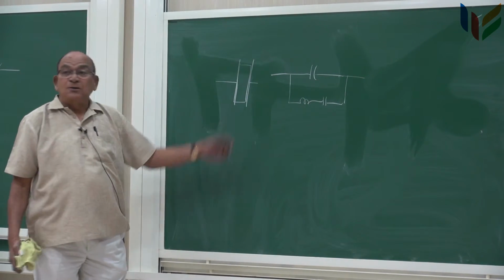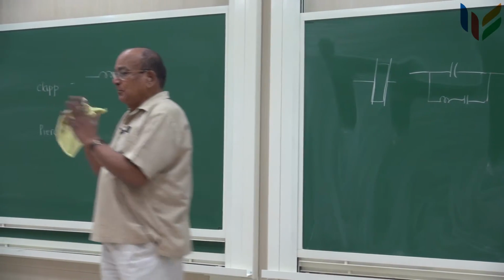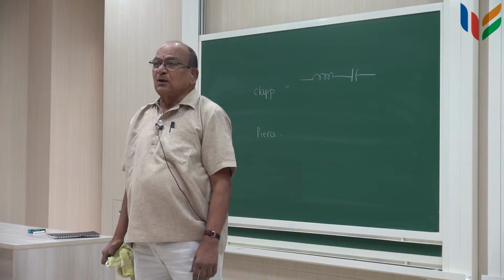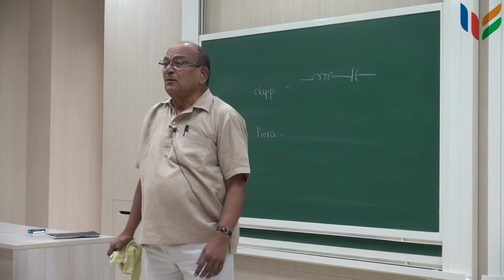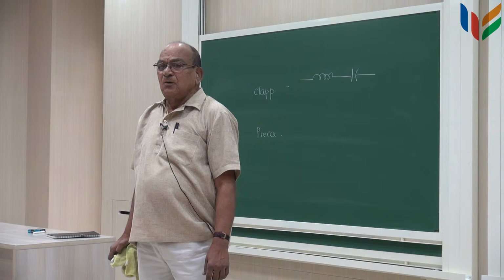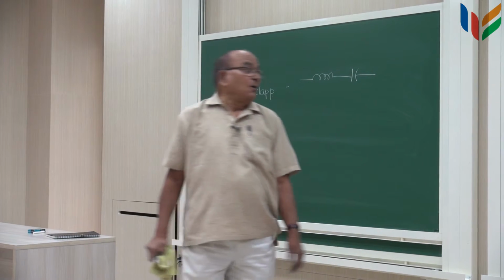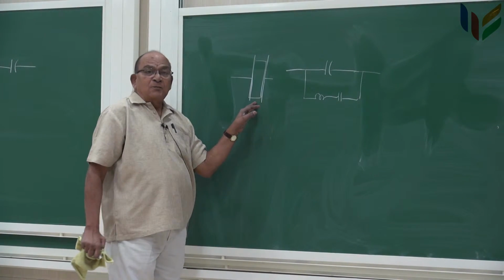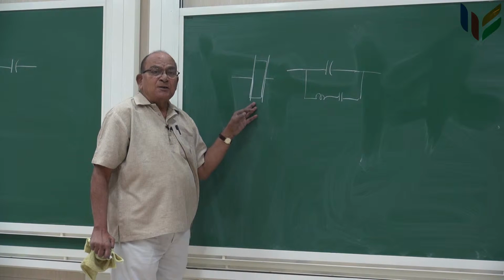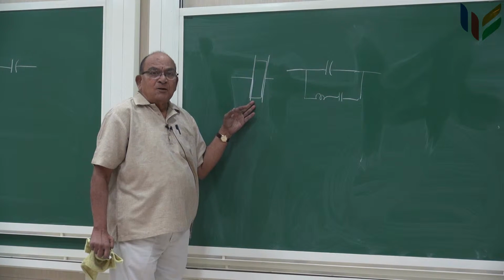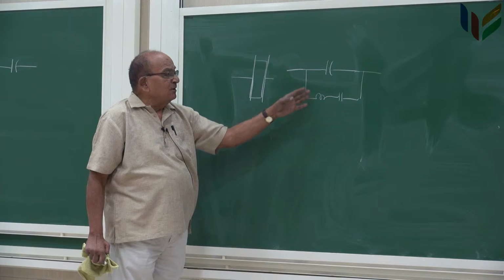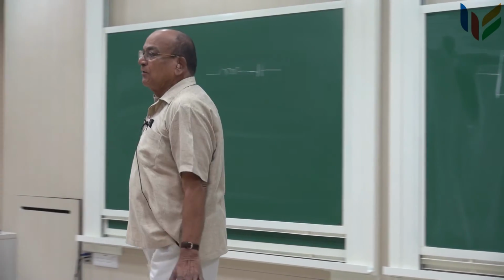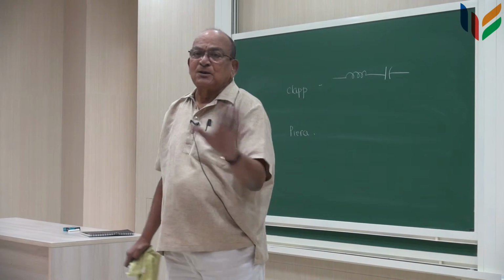This piece of quartz is put between two electrodes, two plates like a capacitor, and this one has an equivalent electrical circuit given by what I have written here. And the beauty of this quartz is that it is comparatively much less sensitive to variation in the temperature. So, all the resonant frequencies associated with this network are very stable even when the temperature changes.